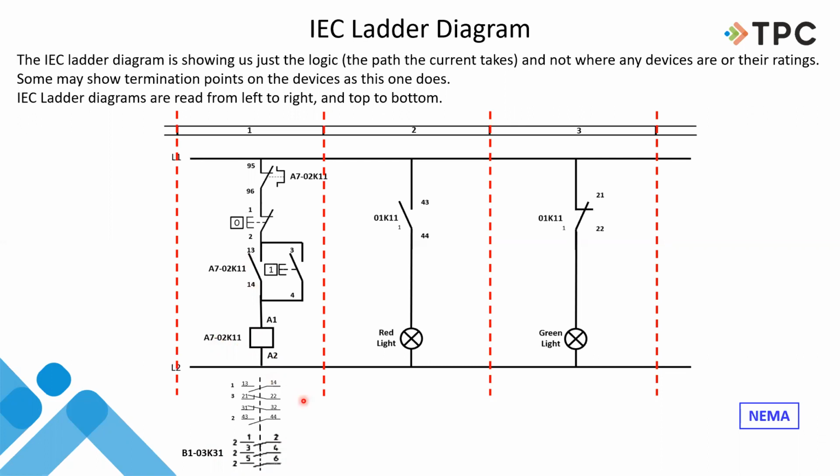So one of the things we talked about is how do I know whether that's a relay or whether that's a contactor? Well, this one is a relay with auxiliaries on it. And I know that because all these contacts that are showing here are double-digit numbers. So remember, 3 and 4 tell me it's open, but the 1 in front of them is telling me it's the first contact on that relay. So I have all of these. This is what's on my auxiliary contacts.